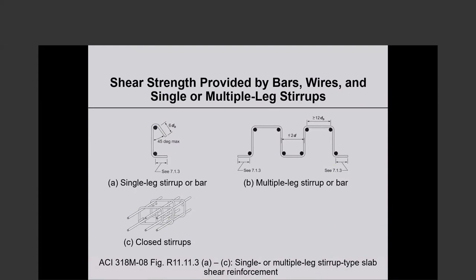But all this shear reinforcement is labor intensive, and right now in this country, I don't want to say this is obsolete, but this is seldom used. What has taken over is the headed shear stud reinforcement, which is a whole lot simpler than all of this. Okay, but this is fully permitted.